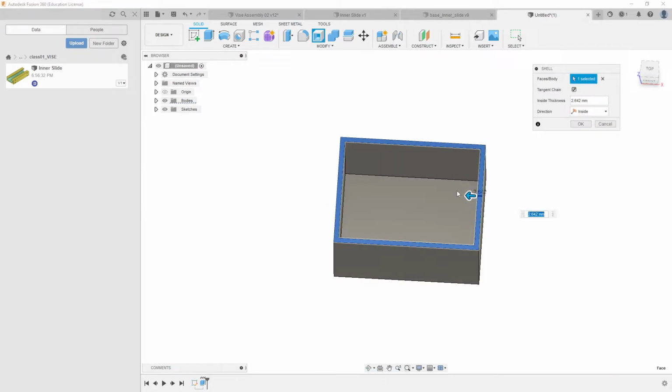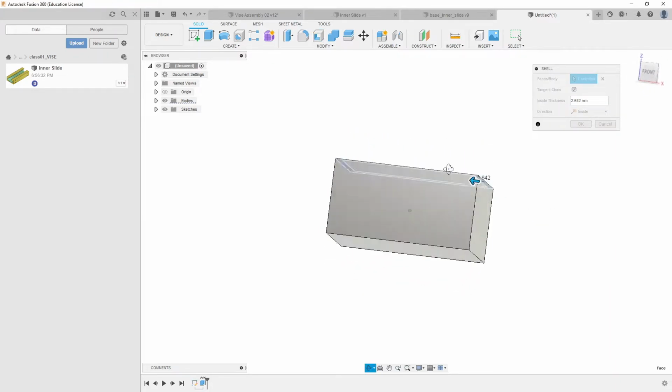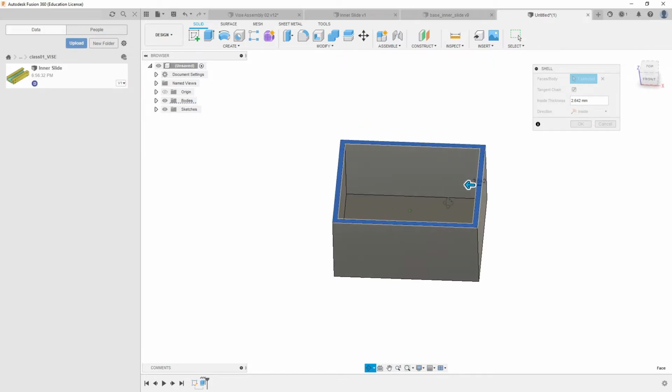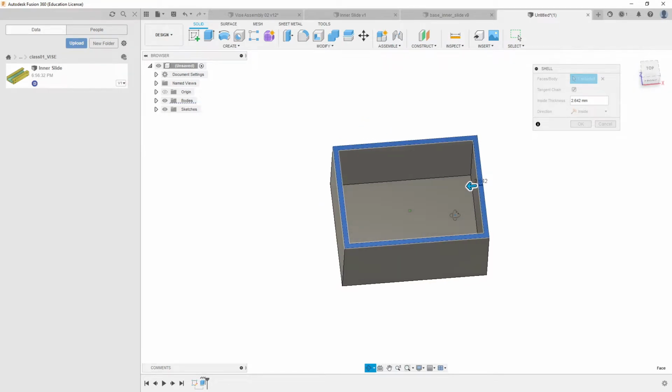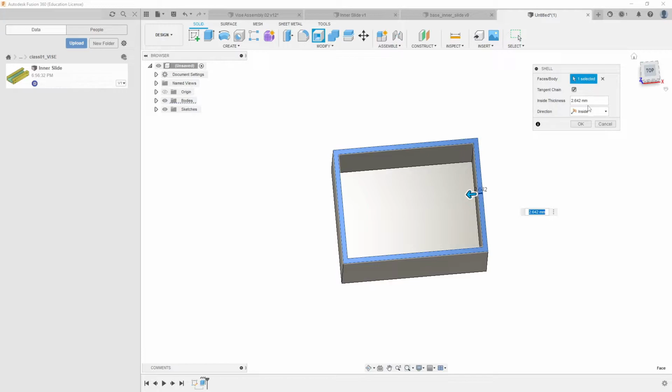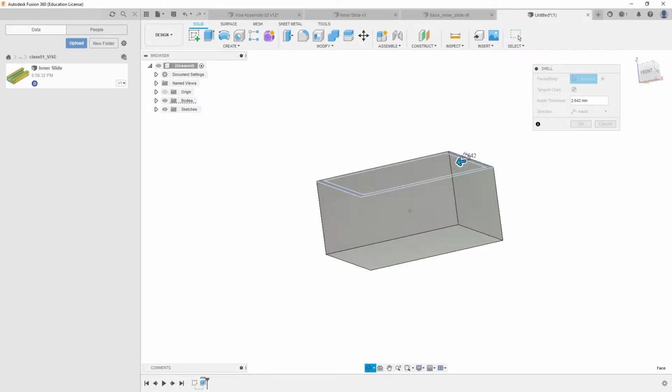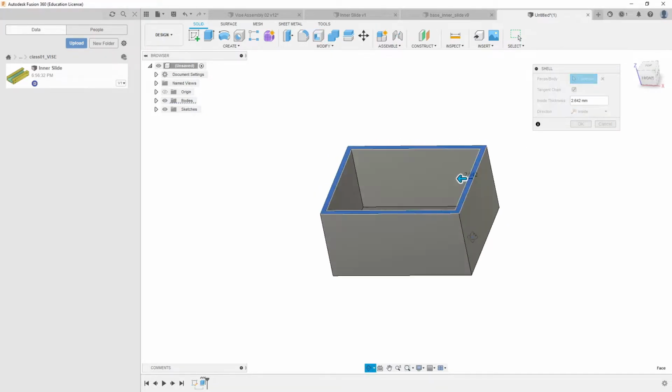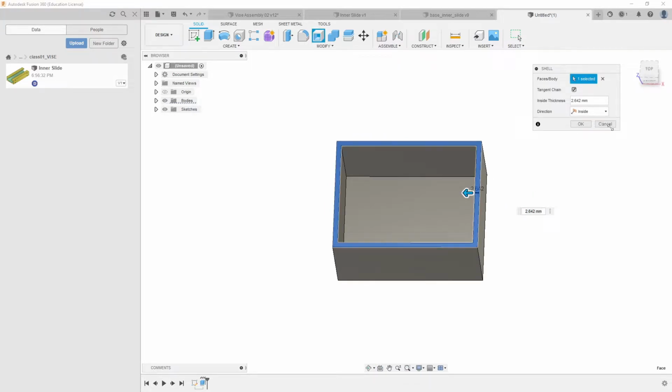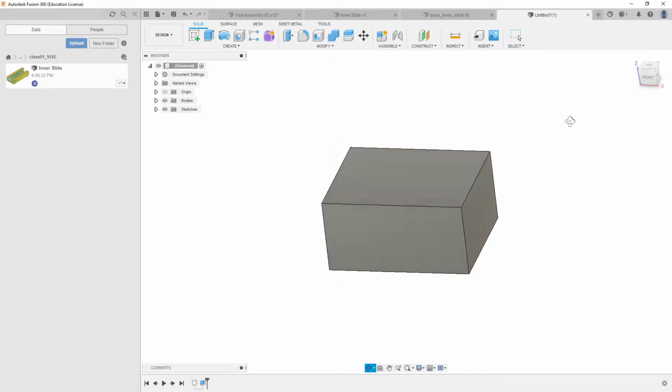So now I have a box, right? A hollow box right here that has a uniform thickness on all sides of this mount, 2.642. But that's also inclusive on the bottom down here as well. The entire thing, all walls are that, right? So let me cancel that. What I'd like you to maybe think of it as is remove face and leave thickness.